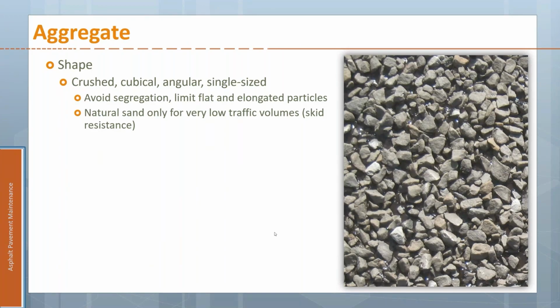Some people will do a sand seal, which I think when they say that, they're meaning like a chip seal, but they're putting sand on that. This is a skid resistance problem in a lot of cases. So this is something I would only recommend for very, very low traffic volumes.